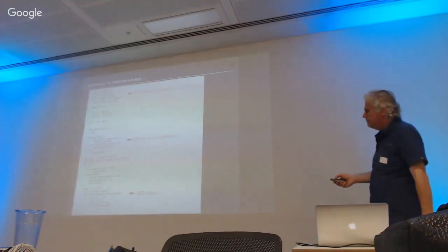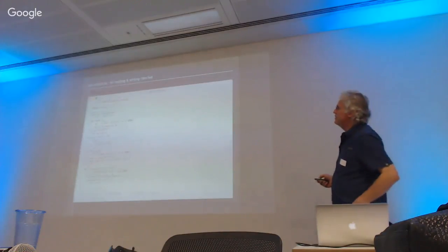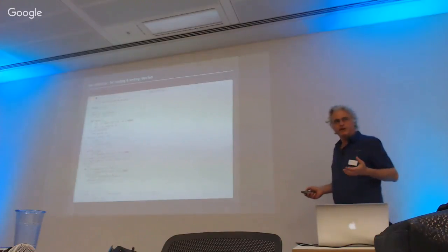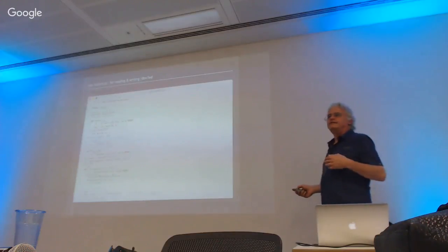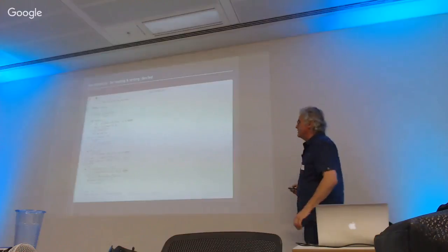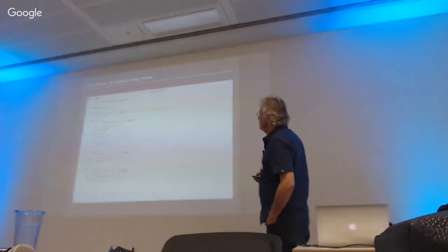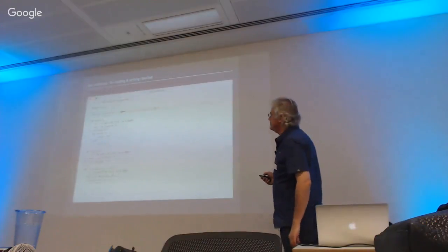Then the actual bit of code, this is in a separate file called LED control.py, which sets up that buffer that we were talking about in user space, where we can send a 1 or a 0 to, which then gets sucked into the driver to turn the LED on and off. That's what this code basically does. So here we reference this file, the interface file /dev/LED that we created before.